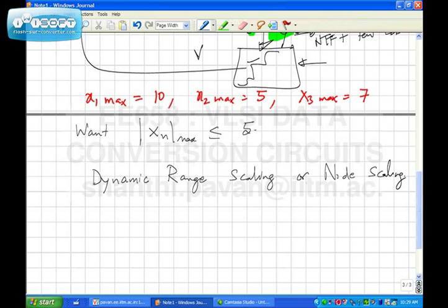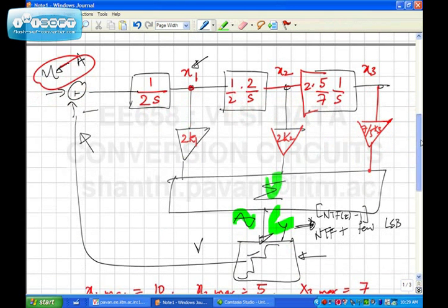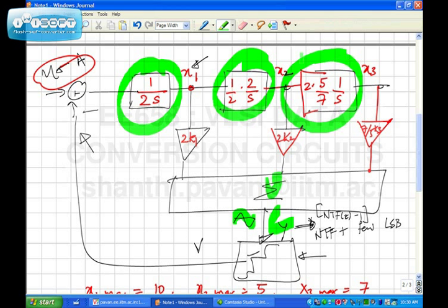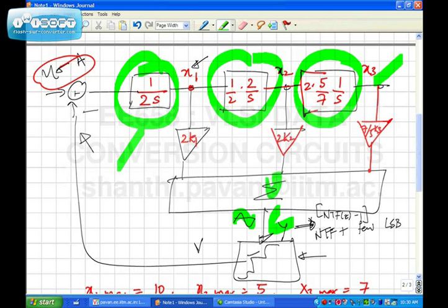So in general, you try to make this X as the noise of the op amp, right? Like you're using generally the same op amp for all the three. No, it depends, right? You could, for example, use different op amps because the thermal noise requirements on, I have not covered it here, but the thermal noise requirements on the first integrator are the most stringent, whereas these can be much noisier. So I would use cheap low power op amps for these two guys and use a solid op amp for this chap. The swing here is the most important, right?